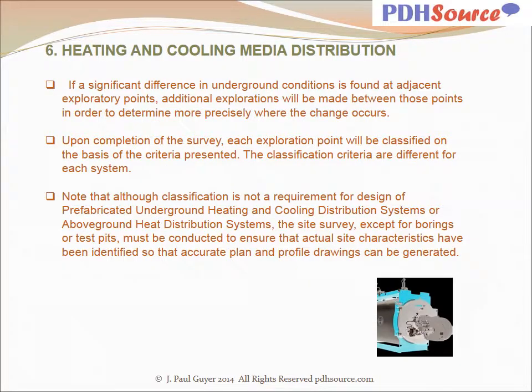If a significant difference in underground conditions is found at adjacent exploratory points, additional explorations will be made between these points in order to determine more precisely where the change occurs. Upon completion of the survey, each exploration point will be classified on the basis of the criteria presented. The classification criteria are different for each system.